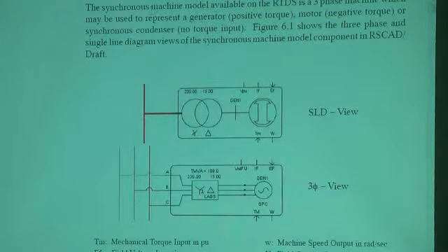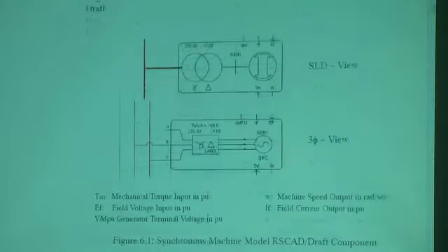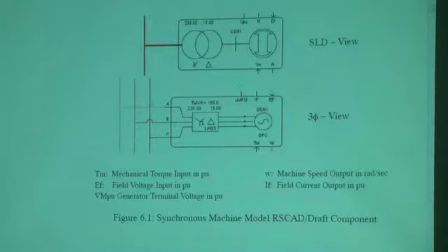The synchronous machine model is a three-phase machine. Again, like the induction machine, generator if it's positive torque, motor negative torque, synchronous condenser with no torque. We have a single line diagram view and a three-phase view. The inputs and outputs are shown here.